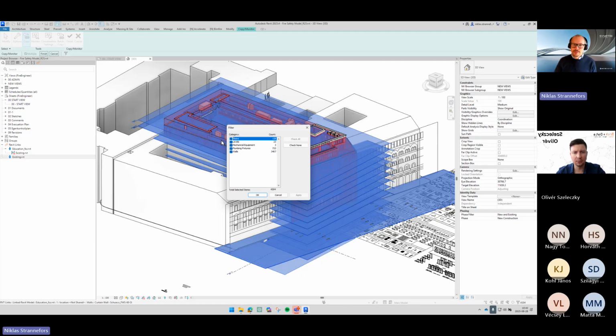And we can deselect floors, walls, mechanical equipment, plumbing fixtures, walls. We only select those 23 levels. And those 23 levels, we're not even going to use all of them, because in this case, they have one level for the architectural floor and one level for the bottom structural floor, so that when they're designing their walls, it goes from the top of the slab to the bottom of the next slab.